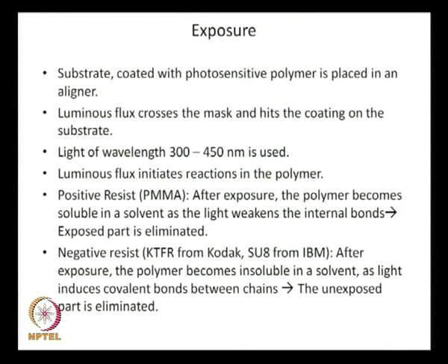Now, the definition of positive resist is that after exposure the polymer becomes soluble in a solvent as the light weakens the internal bonds. So, the exposed part is eliminated. And for negative resist, after exposure the polymer becomes insoluble in a solvent as light induces covalent bonds between chains.